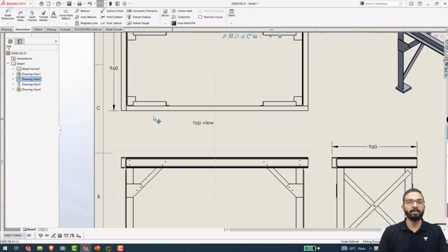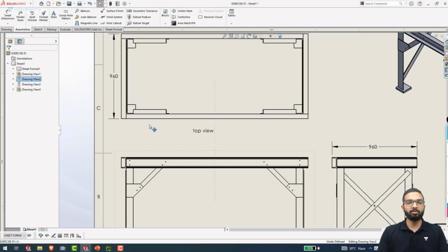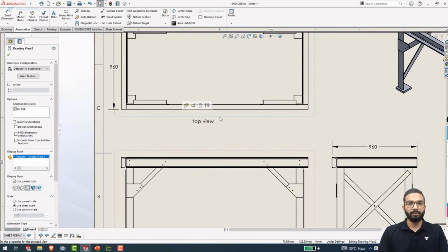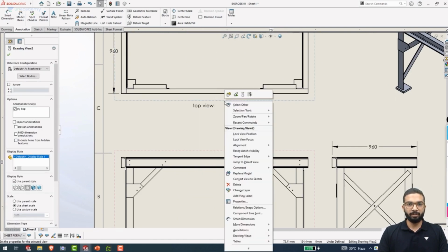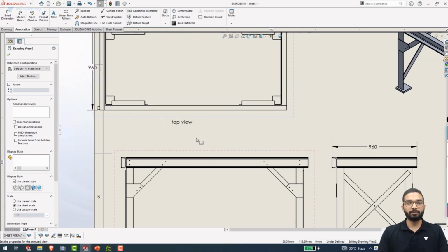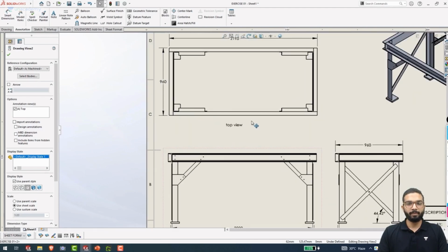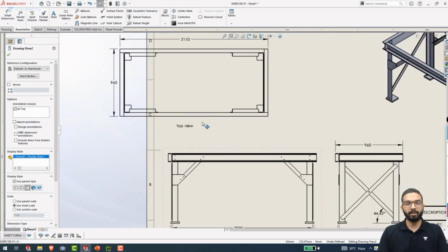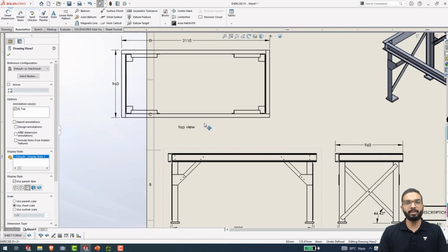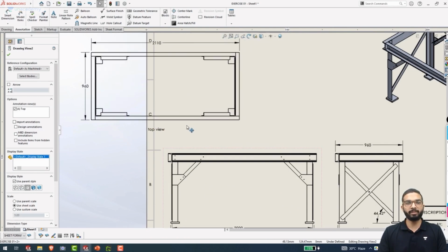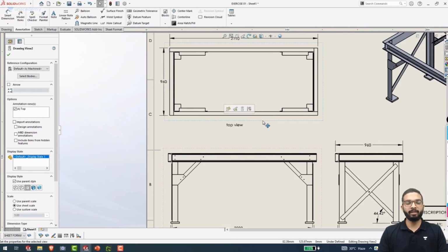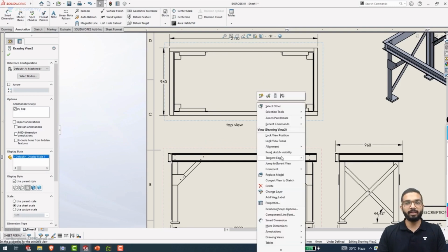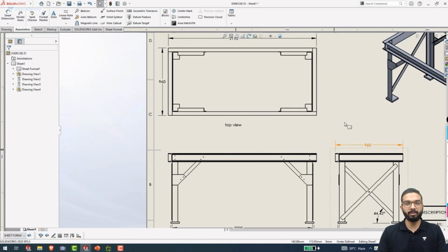But let's say if I try to move this drawing, I will now first break its alignment. So yes, okay, let's say I am trying to move this line over here. You can see that the label is moving along with it. So this is why you have to add the label properly so that it is being aligned to your drawing. Again, I will set it at an alignment, align vertical by center. I will select this line over here and it is now again aligned.